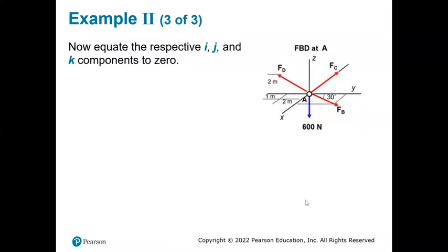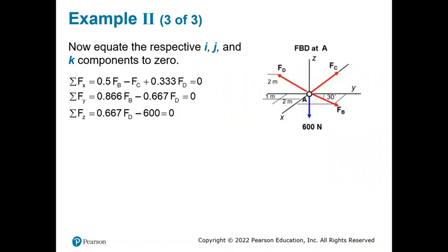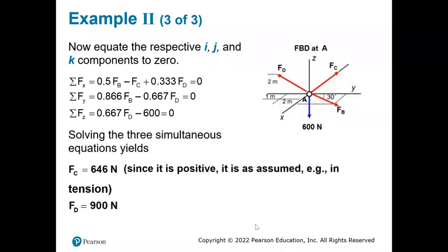Now let's equate the forces to 0, and then you should be able to solve. From the third equation, we can directly get FD, then substitute here and get FB, and then from the first equation get FC, which gives you the values. I hope you got this close to the answer, or maybe you did it halfway or quarter way correctly. Maybe your approach was correct. I hope maybe you were a little stuck at the position vector part. If for some forces no angles are given, or it's not lying in any direction, but only the position is given or where it is located, then you should immediately know that they have given the position. So I have to get the position vector, then get the unit vector, then get my force in that direction.